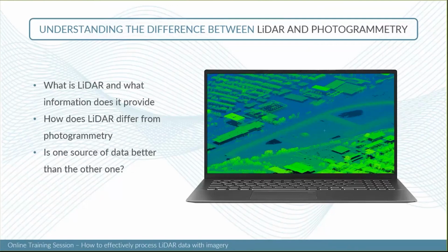And also, it's weather sensitive. Photogrammetry is really reliant on the type of illumination or the type of weather you have when you're collecting your data. You don't really want to have too many shadows in your scene because shadows will affect the texture of your imagery. So the content of your imagery is really important when you're trying to do dense image matching, because low texture will give you some depth perspective problems when matching two images together.